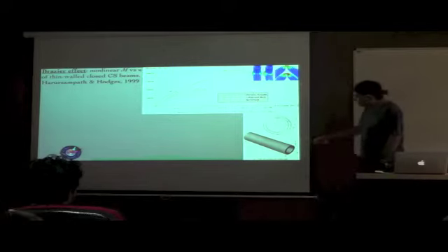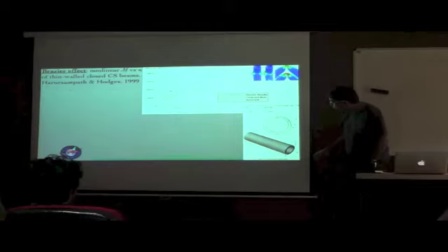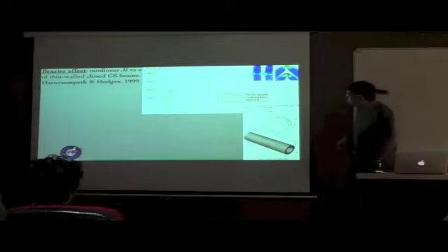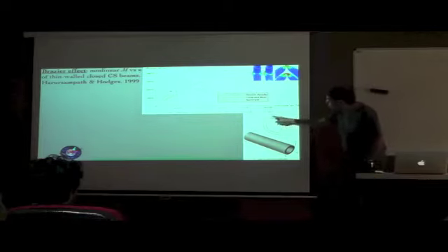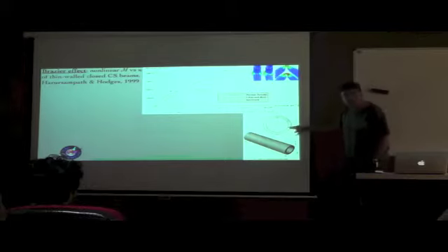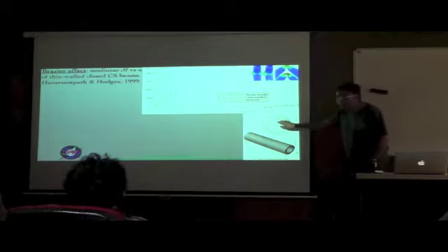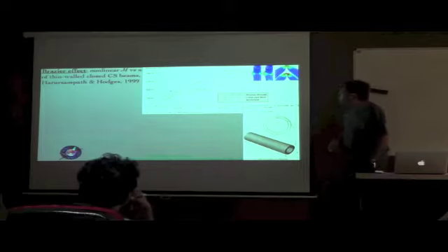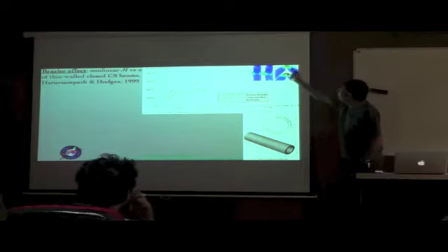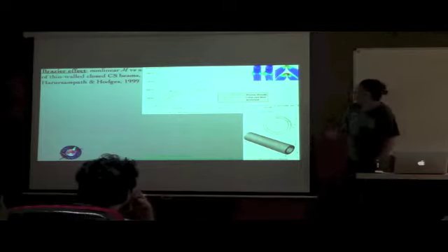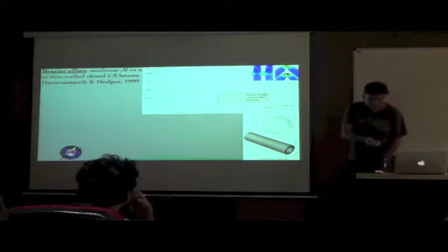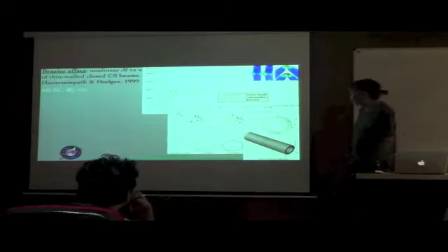So the geometry is basically like this. You have a thin walled circular tube, and you are applying bending moments at both these ends, because of which the original circular cross section starts flattening out, and eventually the limit moment instability takes place, as is shown in this particular discretized picture there.